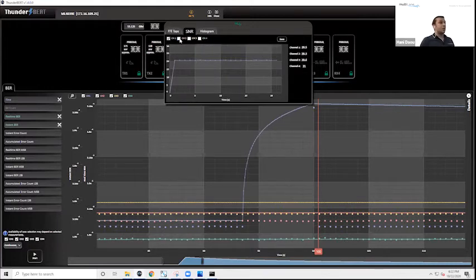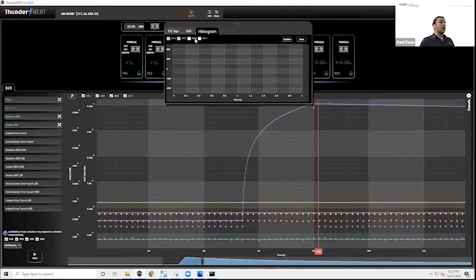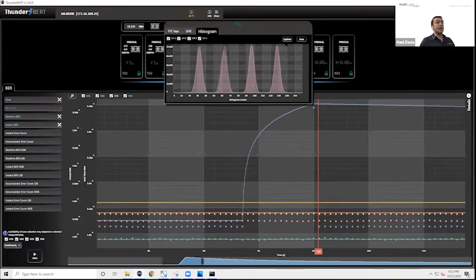But it doesn't stop there. We also offer real-time signal-to-noise ratio of each channel. You can check that out, and you can see the SNR. Right now, it's not so good. It's actually at around 20 dB because, again, I lowered that main equalizer. And another thing I can show you is the histogram. So I'll go ahead and update the histogram, and now you're seeing those 4 logical levels of the PAM4 signal.